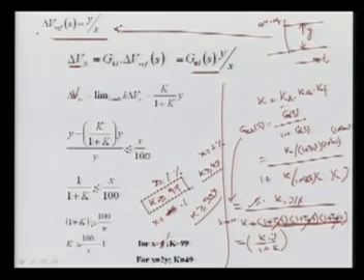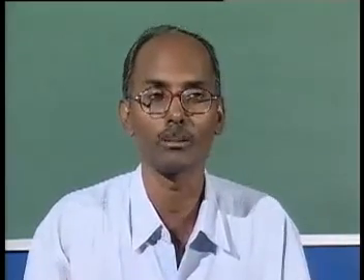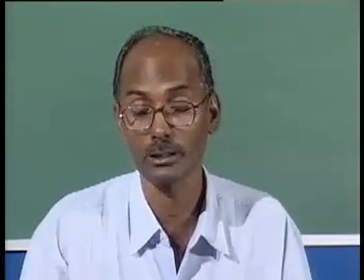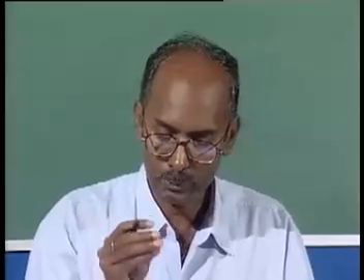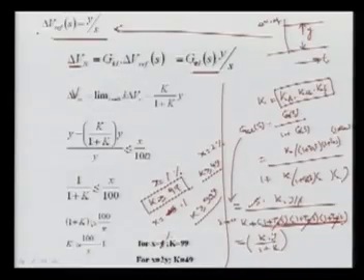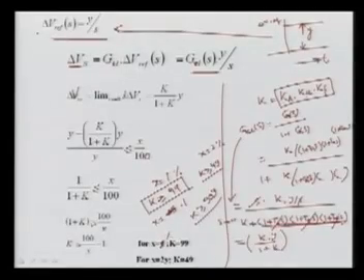Gain means the gain for multiplication of all these three components, Ka, Ke and Kf. Then for the larger gain, you can see for 0%, what happens? If you are putting 0 here, this value is infinite. So you would require a very large value of gain, which is sometimes not possible. It is not possible to realize the infinite gain. So normally, if we are going up to a certain accuracy, we can say our system's static error is 0.